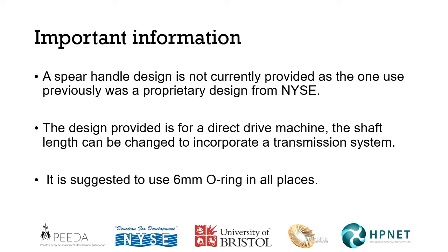Design currently provided is for a direct drive. The shaft could be lengthened and could be used to incorporate a transmission system, and so that adaptation is possible. And throughout the design, it's suggested to use a 6mm O-ring in all the places where there are O-ring grooves.